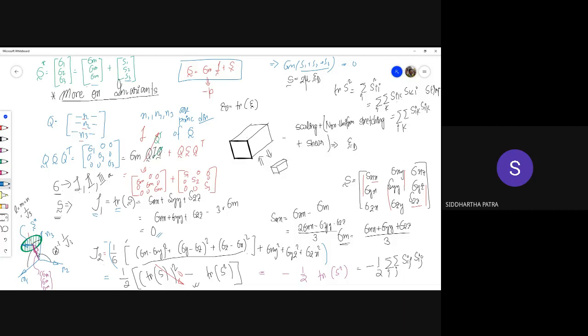So you can imagine a plane that has equal intercept with all three axes. Again, go back to one of our previous classes. We talked about octahedral planes. The octahedral plane on the first quadrant is essentially the deviatoric plane. We talked about octahedral planes in relation to slip, where we discussed the slip planes on an FCC crystal structure. And there we talked about there being 4 octahedral planes, and on each octahedral plane there would be 3 closely packed directions. The octahedral planes are the most densely packed planes.